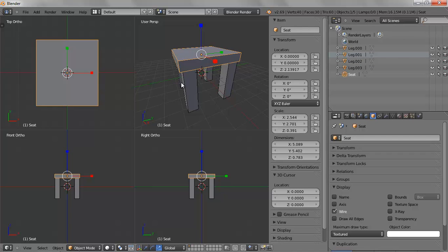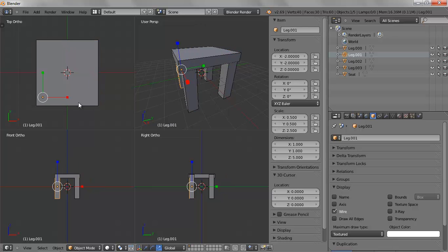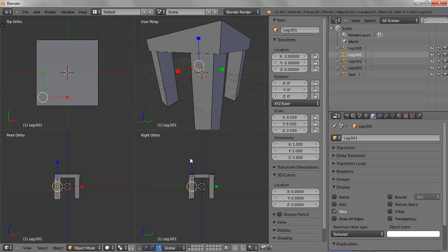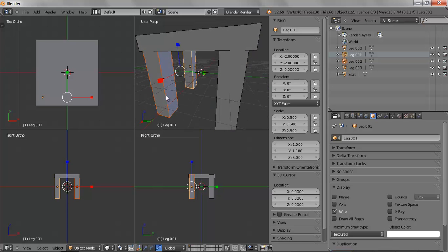For the back, there's a couple ways to do it. We're just going to do a simple way. So let's, from the right view, do a border select. Now if I did a border select, you'll see it went through and selected both objects. There's a setting which will or will not go through visible objects. So by default, you can see we have both of them.